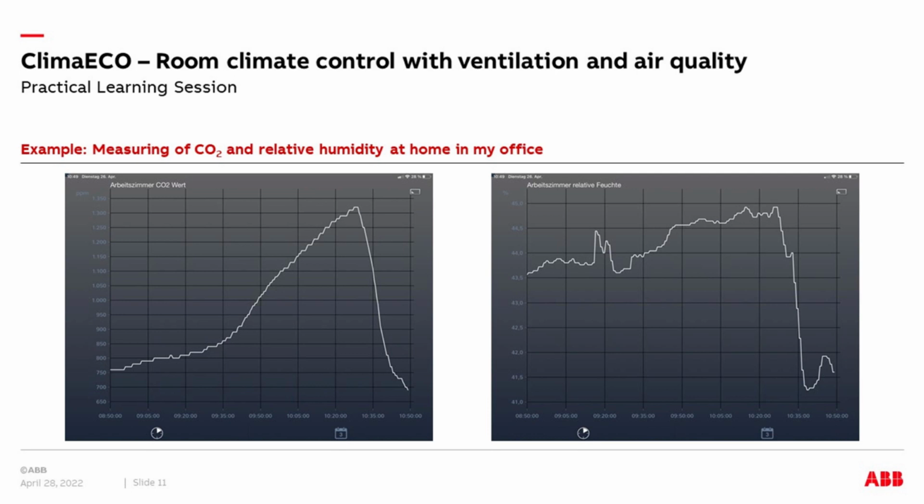And you see the increase of the CO2 level. And then in this case, a window was opened, so simple natural ventilation, and then the value drops. The same more or less for the humidity, the relative humidity. It's increasing as well. And then after ventilation, it's going down again.